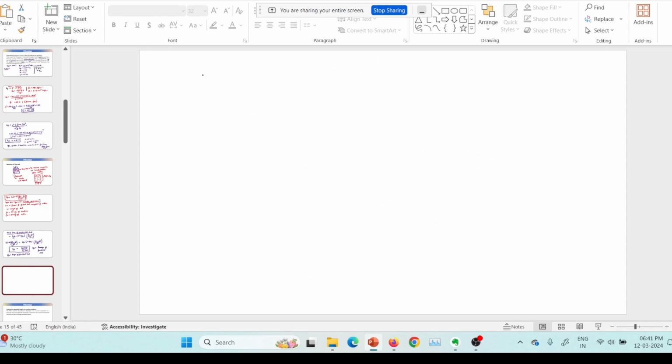This EFB, the porosity of the fluidized bed, is a function of backwash filtering velocity. If I simply write, EFB is VB divided by the terminal settling velocity of the particle, to the power 0.22.